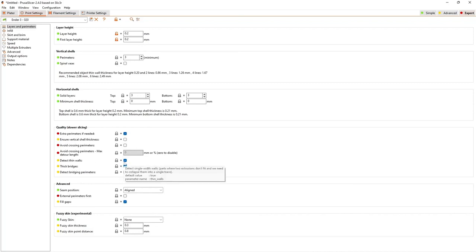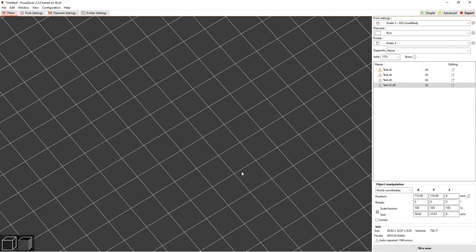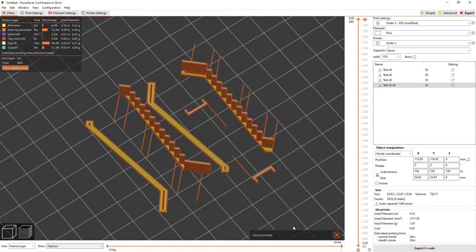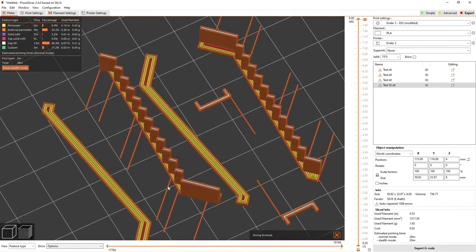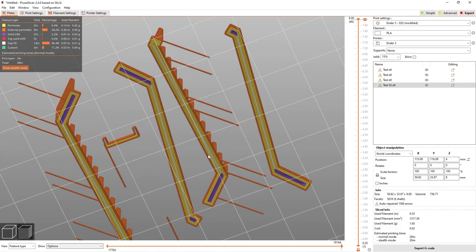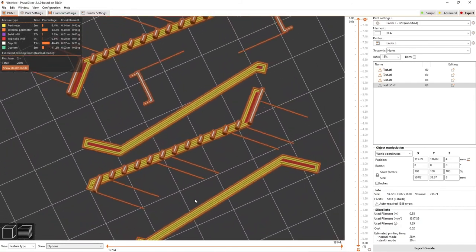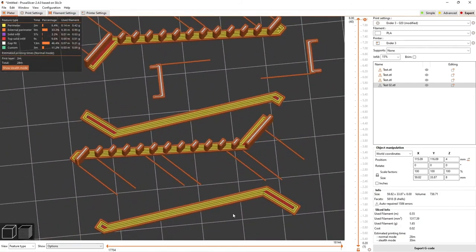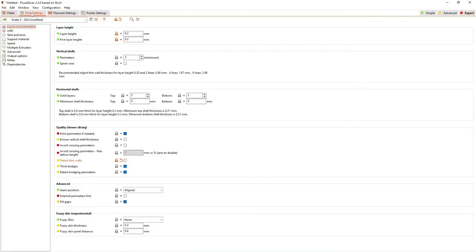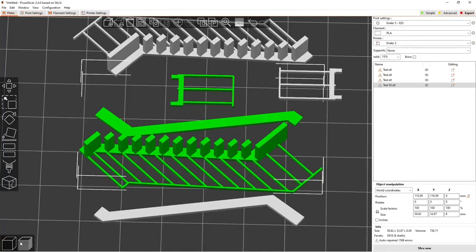You must have that checked. If we uncheck that and go back to the platter, and if you look now, half them bars have gone because we're not detecting thin walls. John was having a problem with that, and it was one in the print settings, detect thin walls. There was just one thing that was out of place,